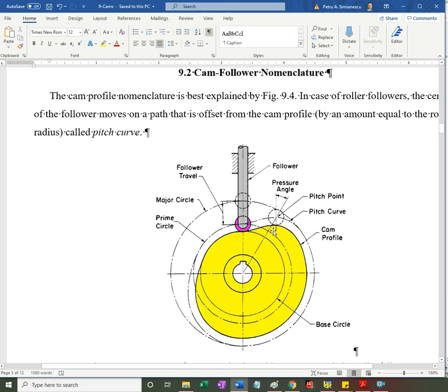And it matters really, because the working against the inertia of everything that I'm driving would be during the rise, again, assuming the direction of rotation of the cam is clockwise, like I said. If I reverse it, I have a faster, jolting motion of the follower, and that is associated with higher acceleration, higher contact forces. On the return, though, it is not as big a concern. You don't want to retract too fast.